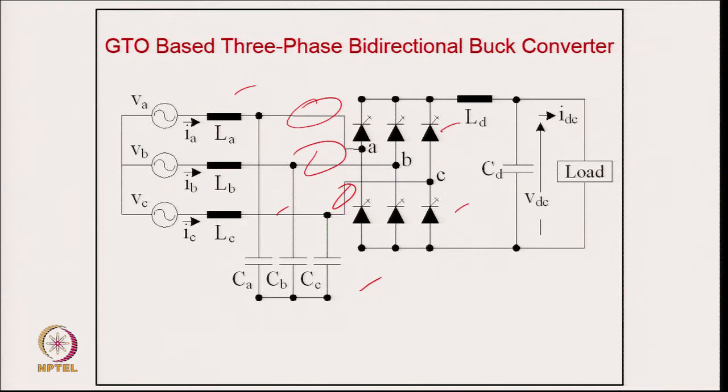Of course, why select a GTO? GTO, the gate turn-off thyristor, has reverse voltage blocking capability, which this current source converter needs here. Of course, the limitation is that the GTO cannot operate at high switching frequency, so you cannot have a lower filter size. But you can use the IGBT with series diode for this converter. That allows higher switching frequency, and you can reduce the size of the EMI filter or output inductor, especially for 3 phase.